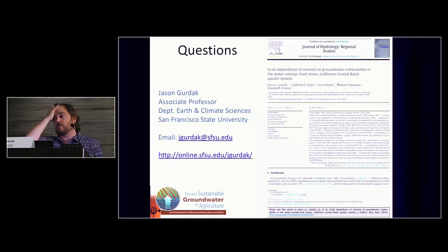You didn't tell where the oxygen measurements for your model were taken, because my experience is that very often oxygen measurements are very poor, because they're really easy to make, but they're just as easy to pollute because there's this huge impact from the atmosphere. So I often see that if you go below 1 milligram per liter, there's a great risk that the sample is contaminated. Do you think that can have any effect on what you saw?